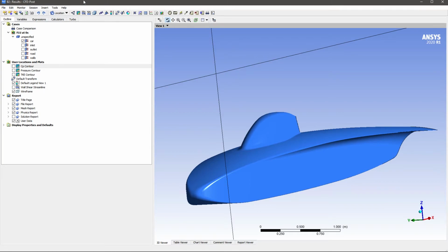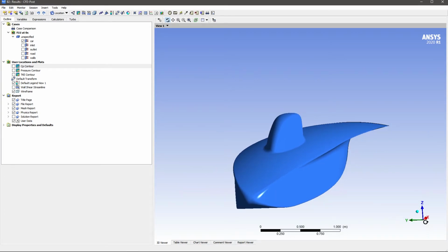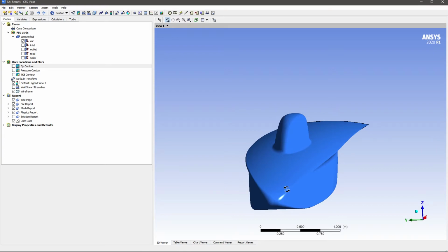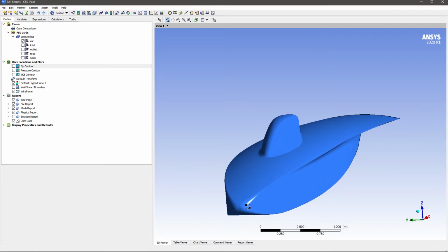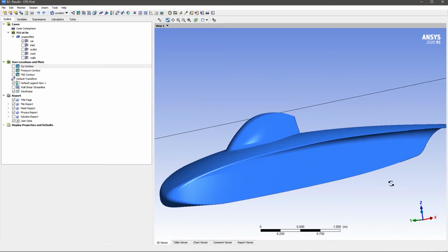We can start off here by being aware of our reference frame. If we're trying to sample a line along the center line of the car, then it's probably going to be of one constant coordinate, and that will be the y equals 0 coordinate. We would also need to know that if we were trying to sample a location along that line, it's best to know that the location is going to be in the x direction, not so much the z direction, as a unique x coordinate will only give us one of two possible points, one region above or below the car.